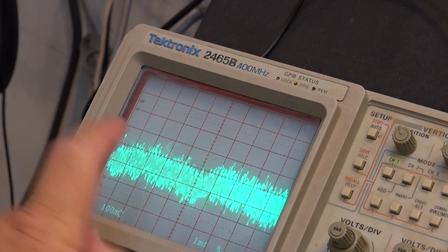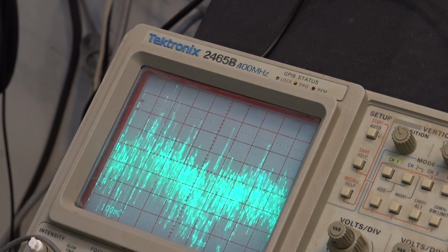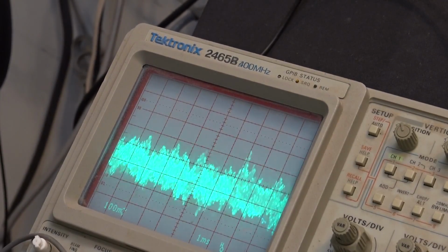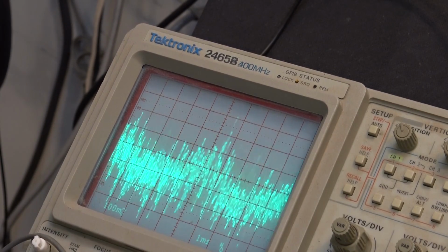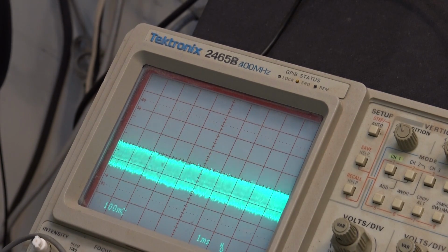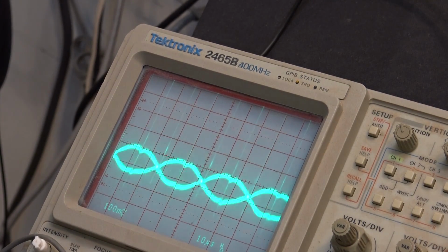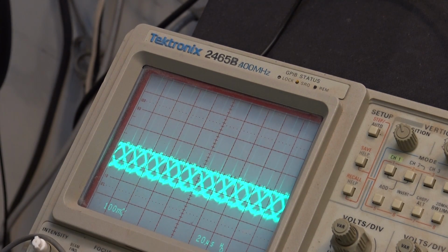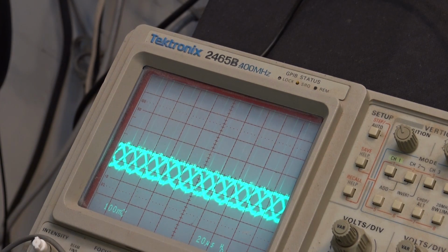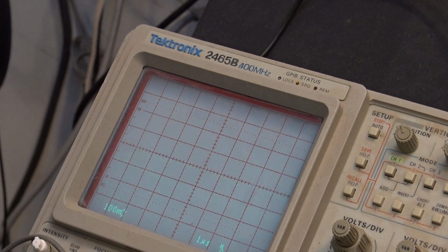If I were to turn off the sound, it would look like there was a carrier. So if I go and unplug the memory stick that's playing on that thing, okay, now you can appreciate it. This is the stereo difference signal. If I crank up, you will see there's a carrier there. That's the 19 kilohertz pilot tone you're probably seeing there. Because the 38 kilohertz difference signal, there wouldn't be anything on that right now because I'm not actually transmitting anything. So what we're seeing here is going to be the pilot tone that's present.